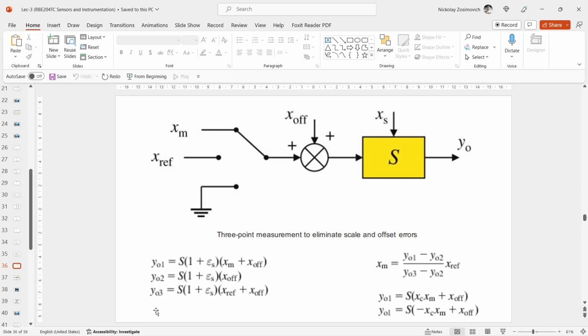This is not the case for many other physical quantities, because repetitively short-circuiting the input of a magnetic field sensor or a force sensor, for instance, without removing the measurand itself, requires complicated and therefore impractical shielding techniques.